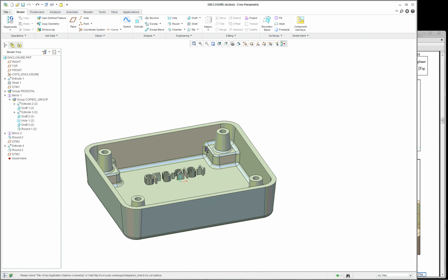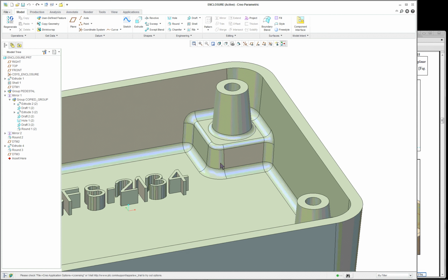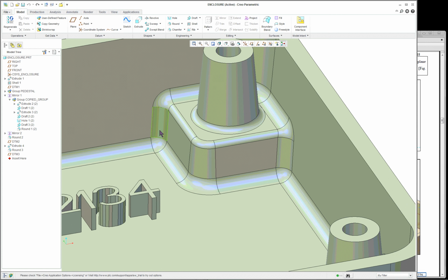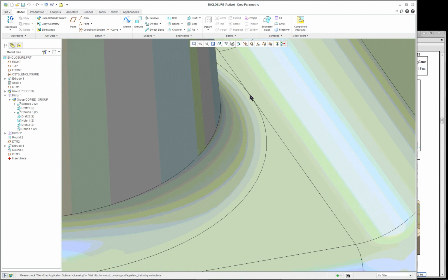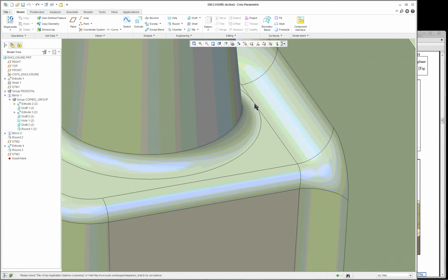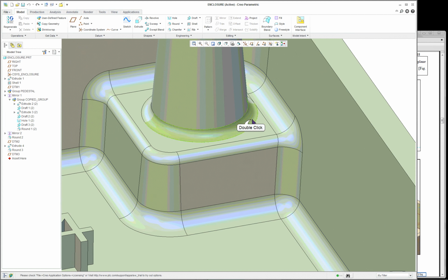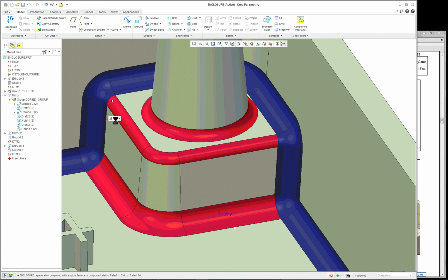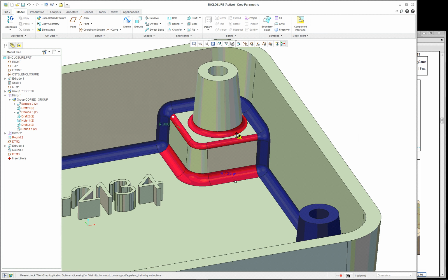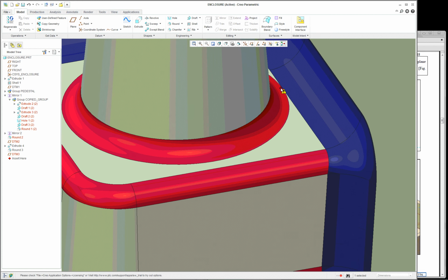Let's go all the way back out. So it's very powerful. Put that surface in there and then solidify it. So if you have a difficulty, I mean, look at how close this is. These are right up against each other. And you can test to see whether or not they are going to work. Let's make this one a little bit bigger. And you can see all this fails by making it bigger because it's interfering here.